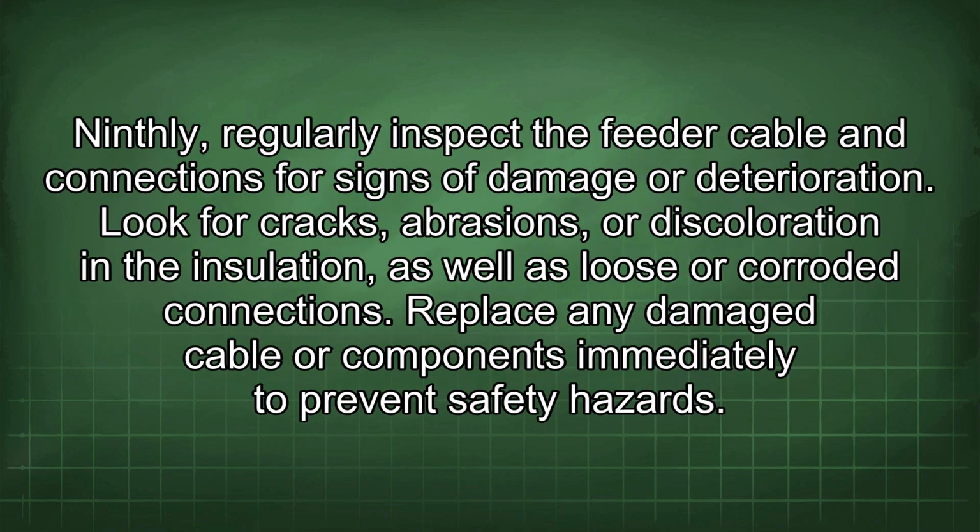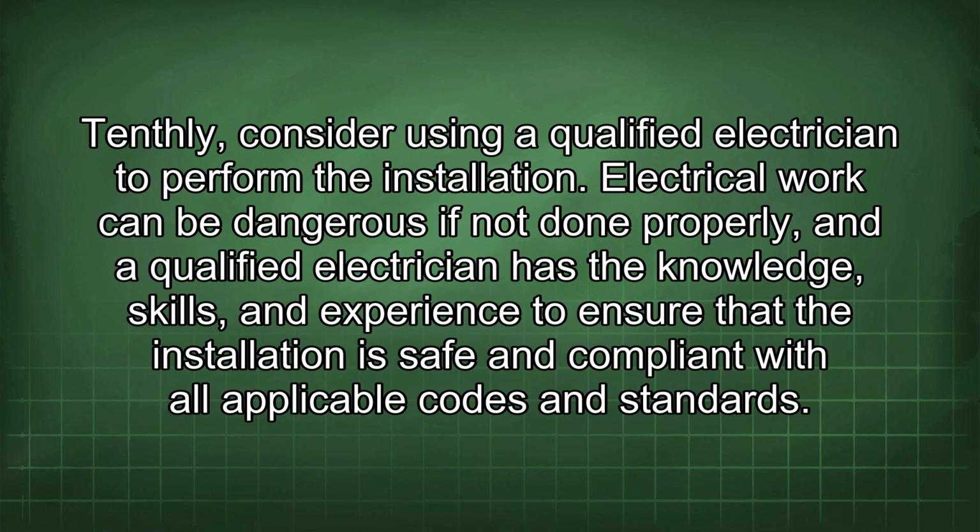Ninthly, regularly inspect the feeder cable and connections for signs of damage or deterioration. Look for cracks, abrasions, or discoloration in the insulation, as well as loose or corroded connections. Replace any damaged cable or components immediately to prevent safety hazards. Tenthly, consider using a qualified electrician to perform the installation. Electrical work can be dangerous if not done properly, and a qualified electrician has the knowledge, skills, and experience to ensure that the installation is safe and compliant with all applicable codes and standards.